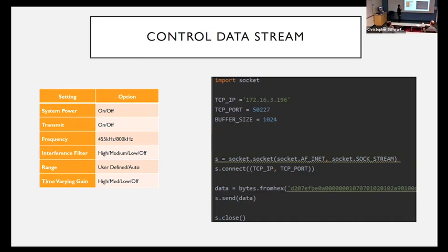The control data stream, I figured this out by, once again, toggling sounder settings right in the bucket. And then eventually I was able to narrow down the packets containing the actual command string, extract the header data, and then finally extract the actual string with the command. Here's a little snippet of one of them. And what I was able to do is package those commands in some Python code that allowed me to build my own network packet and then distribute that command from a computer of my choice. So now we're headlessly controlling the side scan.